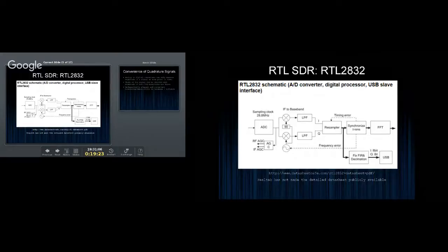But at the same time, there are other digitizing systems that actually produce the digital clock-based quadrature and then mix the RF signal or the intermediate frequency down into in-phase and quadrature using the clock rather than some other means. So that's about as much information as I could find. There's a one-page text description of what this chip does. But as far as the internet community is concerned, there's a bit of hocus pocus, and they'd rather not have you understand it, I believe.